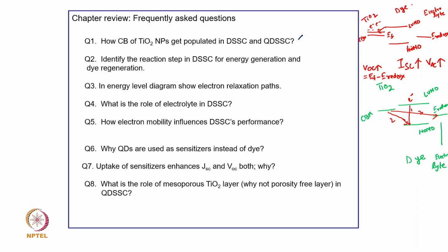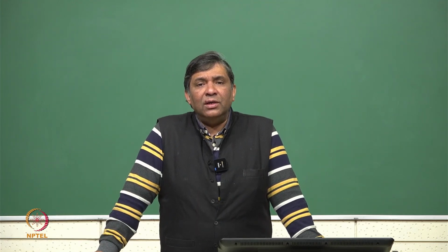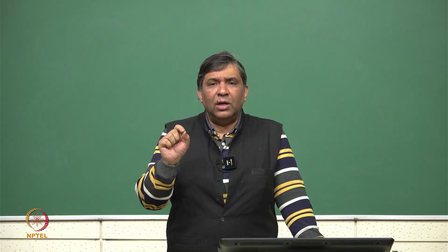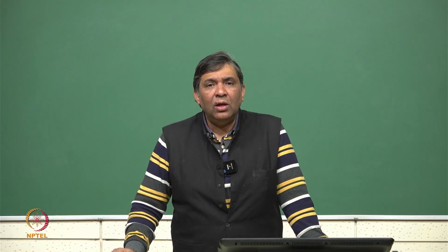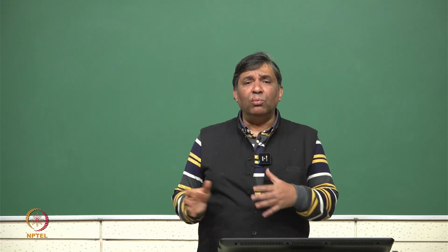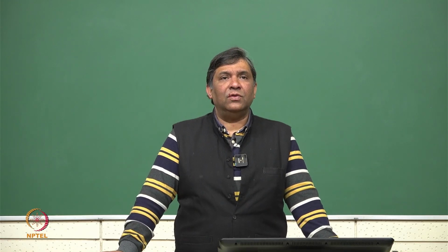along with short circuit current density, open circuit voltage will also increase, but it was different when we talked about mobility. In mobility, what we have seen, the short circuit current density will enhance significantly and open circuit voltage will reduce, but the reduction is very small because of the higher mobility of charge carriers. But in this case, both short circuit current density and open circuit voltage will enhance.